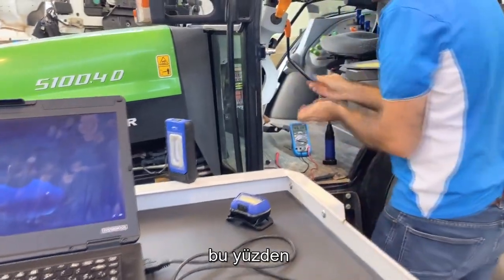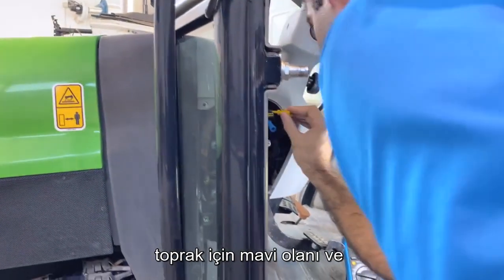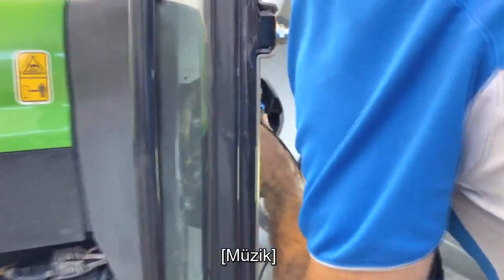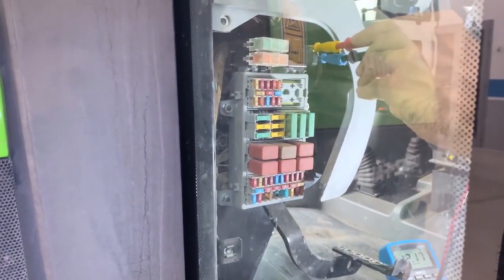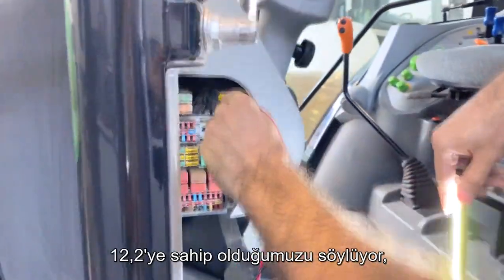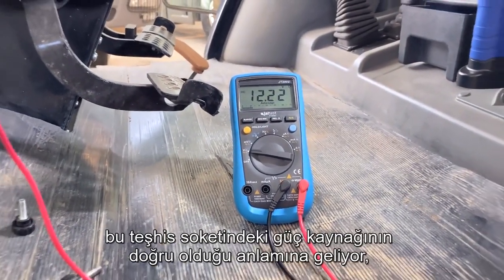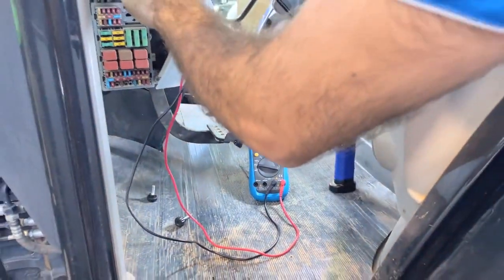Better like this. So I'm going to use the blue one for ground and the yellow one for positive. Now it's in auto range. As you can see, the multimeter says we've got 12.2 volts. That means that the power supply in the diagnostic socket is correct.